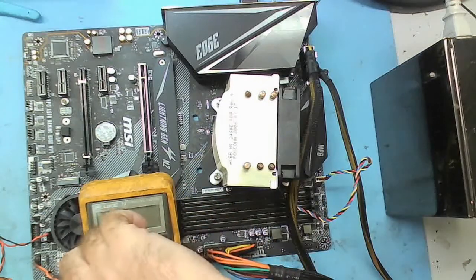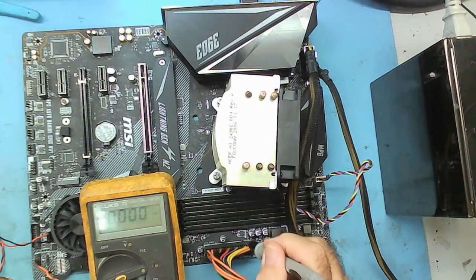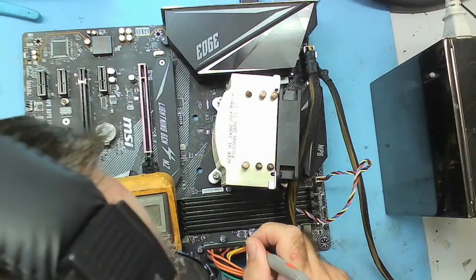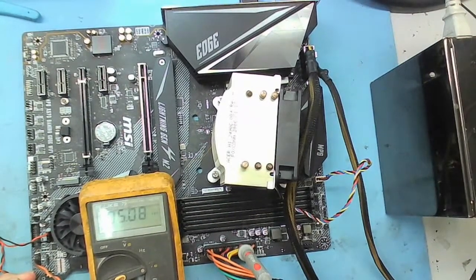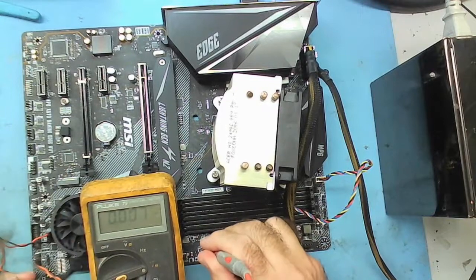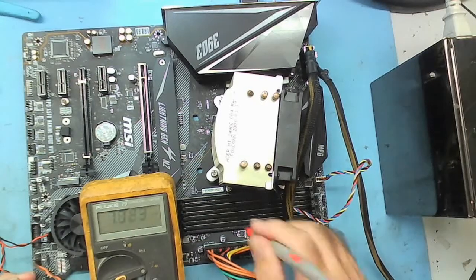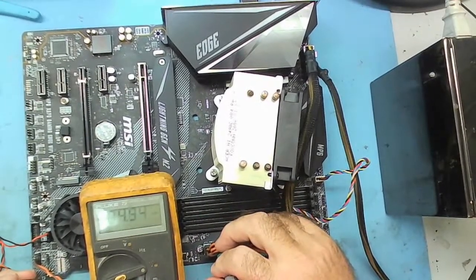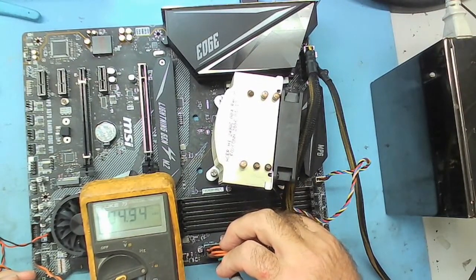Okay, let's have a look. Voltage. Right, first thing I'm going to do is check to see if there's standby 3.3 coming on here, which I think is the purple. I might have to just go check that. But no, it's a purple. It's a bit of the green. Set to ground. 5 volt standby coming in. It's not 3, but it's 5 volt standby coming in. Nothing else. Just in the yellow. No, nothing else. That's not starting. It's on the green. This is effectively your pin that you ground to start a power supply. 4.9 on there on the green, yeah.